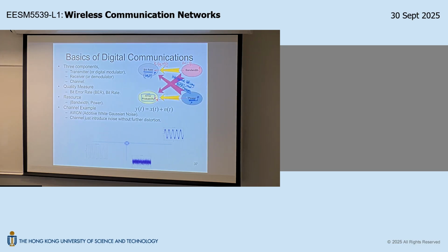As I said, the condition for you to use this is you need to make sure that the signal-to-noise ratio is sufficiently high. Otherwise, the constellation points are too dense together and the error probability will be too high. You need extra power to spread out the constellation points on this QAM constellation. That's why you need to make sure signal-to-noise ratio is sufficiently large. For a cable TV network, this is what we call a noise-limited system.